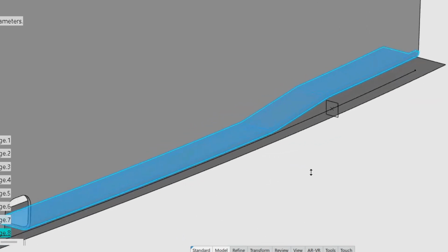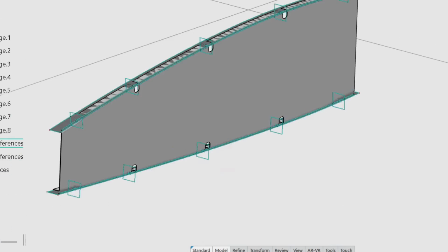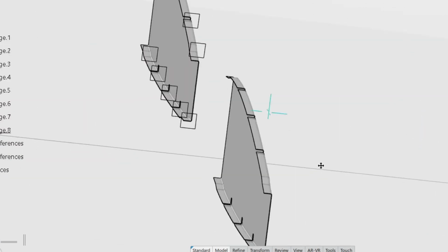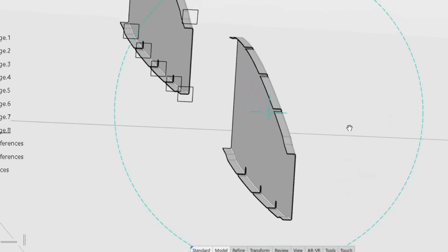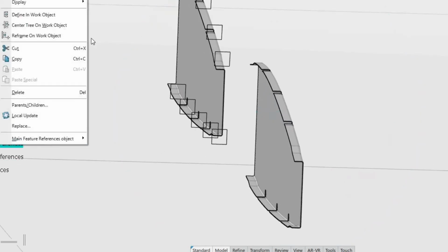In the end, each section of the rib should have a flange, and at each plane, the intersecting flange should have a joggle corresponding to a spar corner or a stringer.